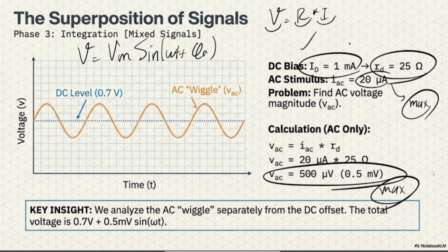So right now I can write down my AC voltage as a formula like this. And why are we adding it with 0.7 volts? Because 0.7 volt is the DC voltage, the amount of voltage your diode is going to have, or the cost for your diode to act normally, in a linear condition.